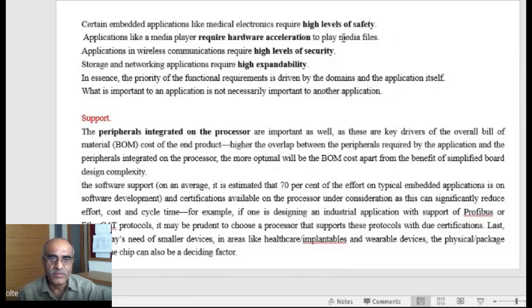For example, here we are taking the EtherCAT protocol. Suppose our industrial application needs the EtherCAT protocol, so the data provided to this CPU is going to be connected along with this protocol. If my CPU comes with this protocol, then I don't require any additional add-on circuitry or add-on software routines along with my system. So at this moment I should check whether such support is there along with the CPU or not, and then I will select such a CPU, isn't it?